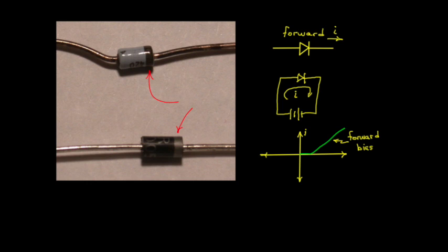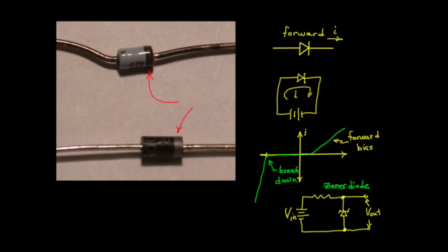When the voltage is applied in the opposite direction, only a very small current flows. However, if we apply a very large reverse bias voltage, the diode barrier eventually breaks down, and current flows easily beyond that point. This property is actually exploited in Zener diodes, which break down at well-defined voltages. A Zener diode can be used to regulate the voltage at a given point in the circuit so that the voltage there never exceeds a designed limit.